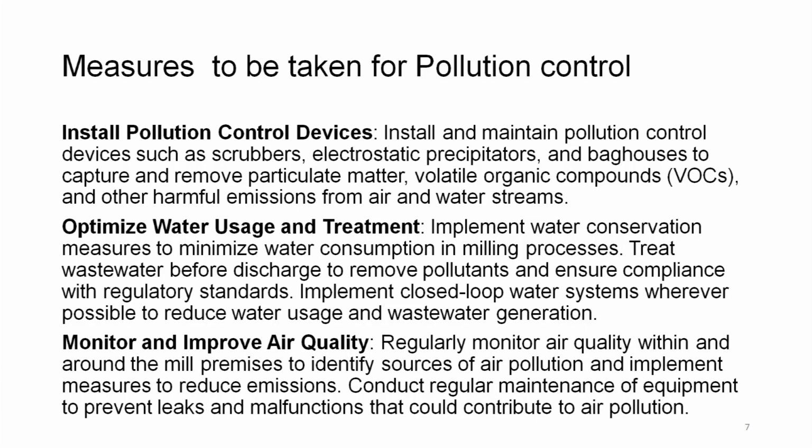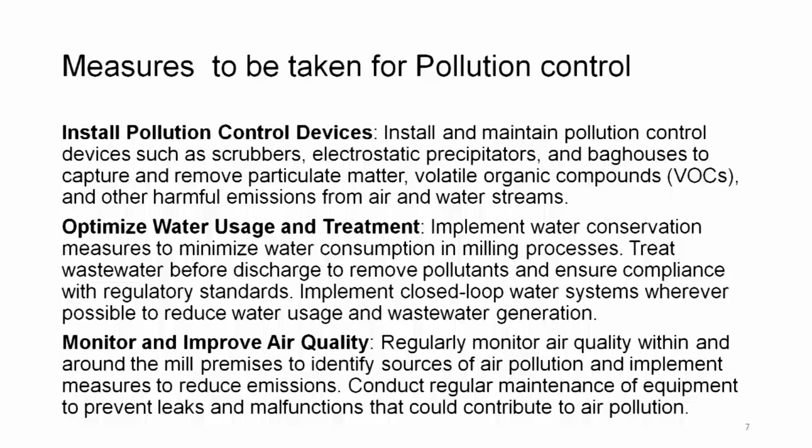Implement closed loop water system wherever possible to reduce water usage and wastewater generation. And we saw that this closed loop water system, where the squeezing water is again reused in the process, or the new dye bath is enhanced with the recovered water, dyed water. So, those kind of practices are very good.